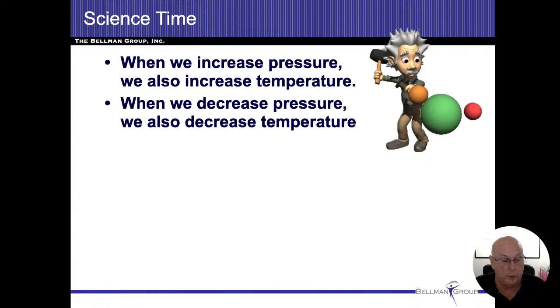And as it converts from a liquid to a gas, it has to absorb a tremendous amount of BTUs. I need you to remember that part. It absorbs a tremendous amount of BTUs. And even on the other end, when we're discharging the heat, we're switching from a gas to a liquid. When we switch from a gas to a liquid, we're discharging a tremendous amount of BTUs.